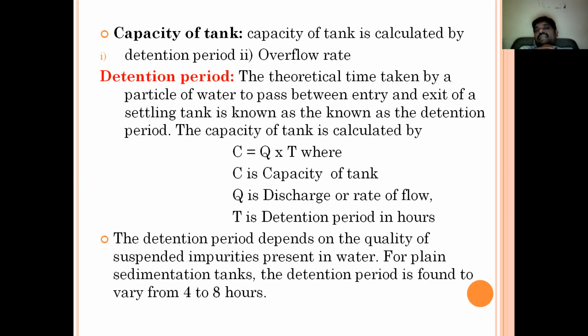So C, the capacity of the tank, is calculated with the formula Q into T. Q means discharge or rate of flow, and T is the detention period in hours. Next point is the detention.